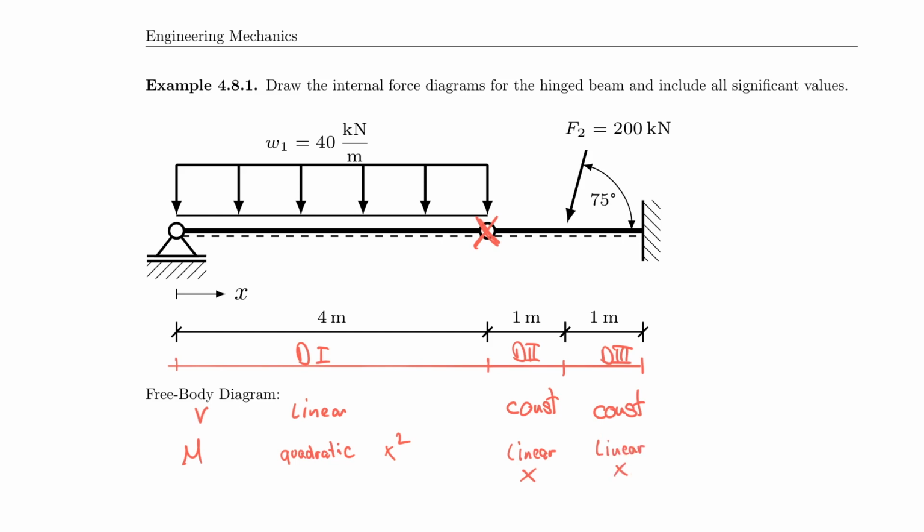So now it's just a matter of solving the problem, and we learned already before that we can break this down into the two subsystems, the cantilever on the right side, the simply supported beam on the left side, and therefore all we have to do now is find the support reaction and use this to solve our problem. I'm going to make my life very easy here because I have a cantilever on the right side.